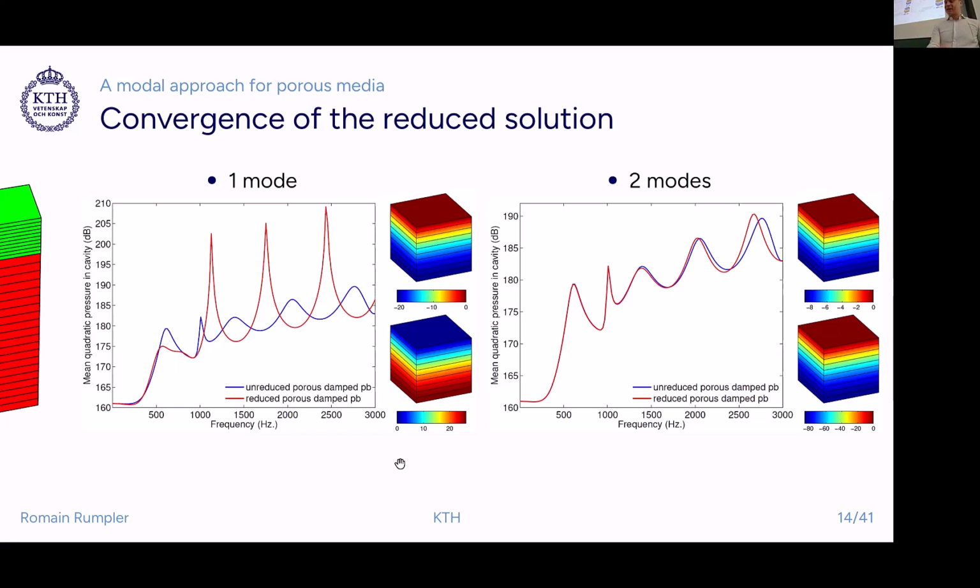And it's very clear that the modes, if we just look at the compressional modes, which are the ones we are considering in this simplified 1D problem, work in pairs. One is the out-of-phase one, and the other one has the different scaling between the solid and fluid phase. And it's only when we have added two of them in the basis to project the whole problem that we have a decent representation of the original full order model.